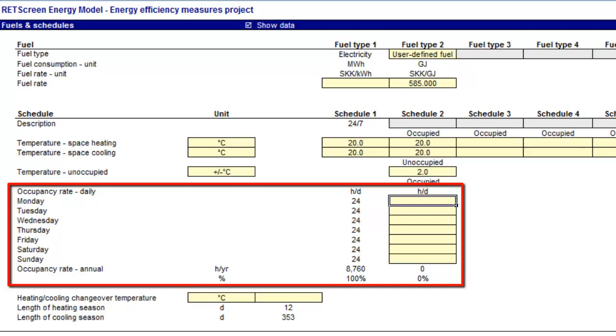In this particular study, since there is no provision to separate the heating loads between the school and the adjoining caretaker flat, the school has to be fully heated during unoccupied times, such as during weekends and summer months. In other circumstances, we could account for closure during certain periods of the year by modifying the heating degree days and cooling degree day values entered in the climate data area of the START worksheet.